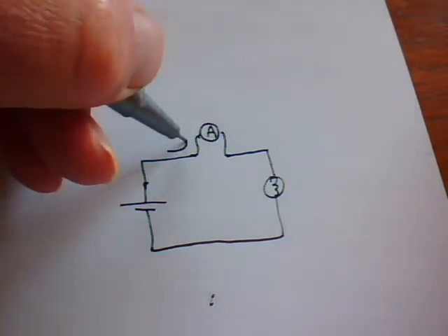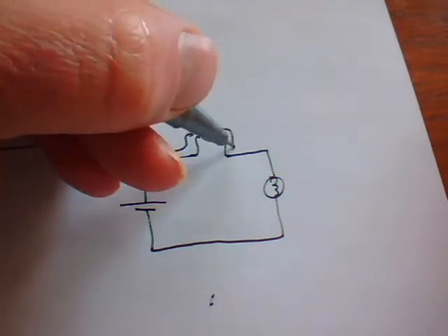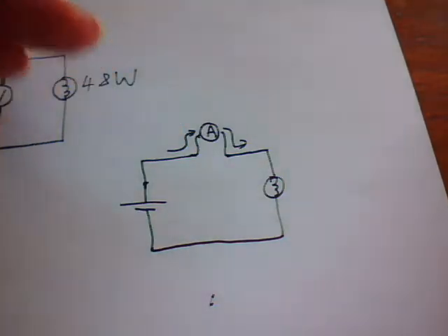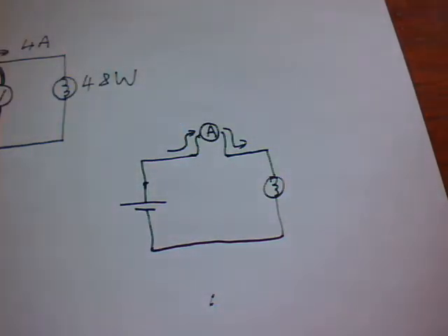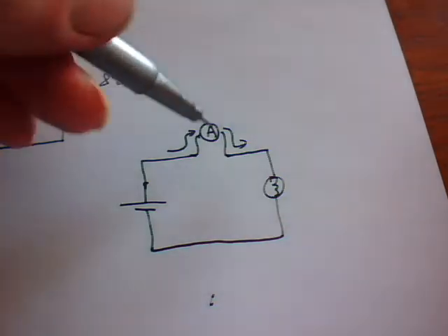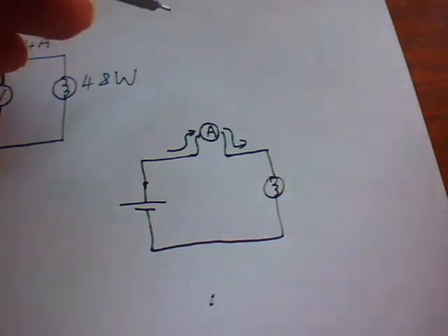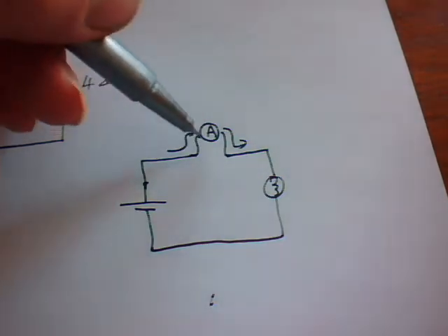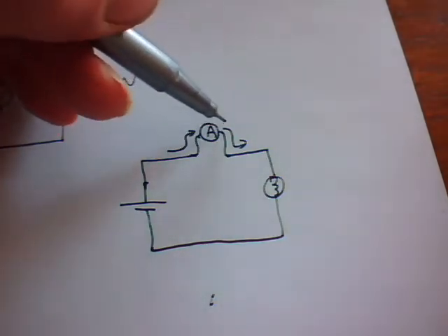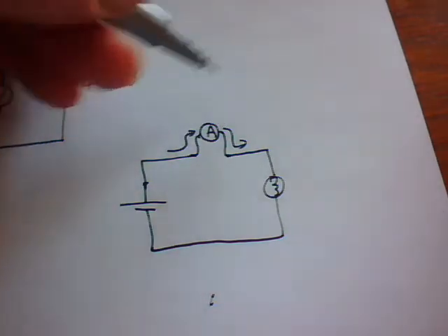So then the current will flow through the ammeter. The ammeter is the name of a device which measures current, so the current has to flow through it. If you try and measure across, then you're going to make some sort of short circuit. The reason why is when you've got your ammeter connected, it acts like an extremely low resistance.